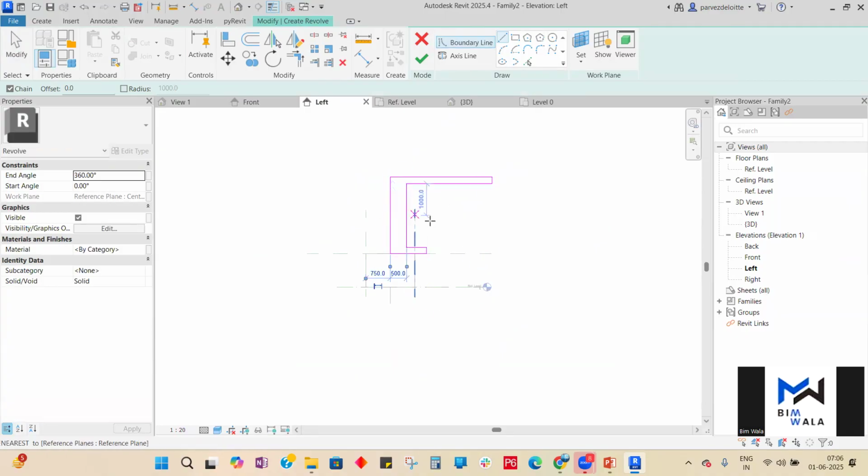Boundary should be closed. जब भी आप कोई ज्योमेट्री बनाएंगे, you need to consider 2 points. It should be a closed loop always. It should not be an open loop. First condition. Second condition is there should not be two lines intersecting each other. Okay. No two lines should be intersecting each other. Now, this is my boundary line.